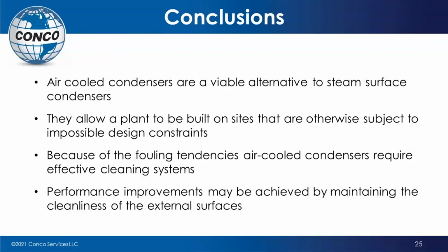They allow a plant to be built wherever without any issues with water. But because of the fouling tendencies of air-cooled condensers, and because of some of the inefficiencies of air itself and some of the problems that you have as far as summer temperatures, it is imperative that the air-cooled condenser be cleaned and effective so that the flow of air is able to get through all those fins and you can utilize those fins extensively to give you the performance improvement that you need.